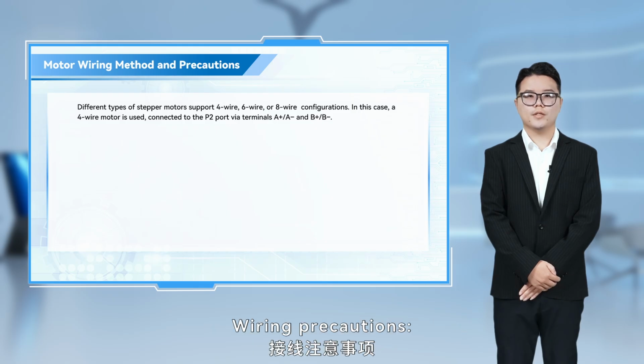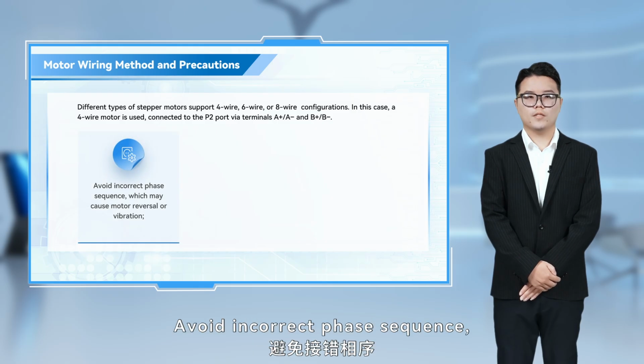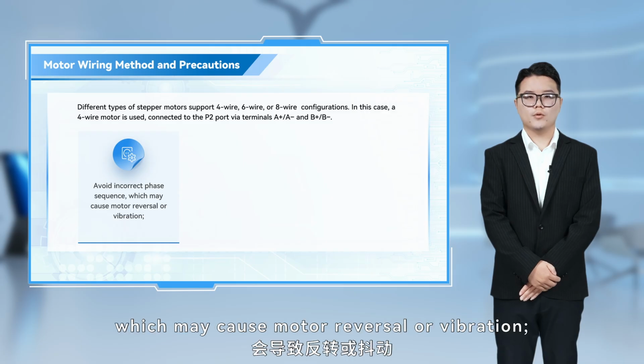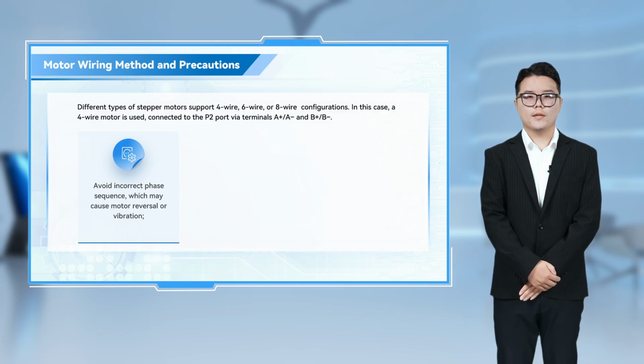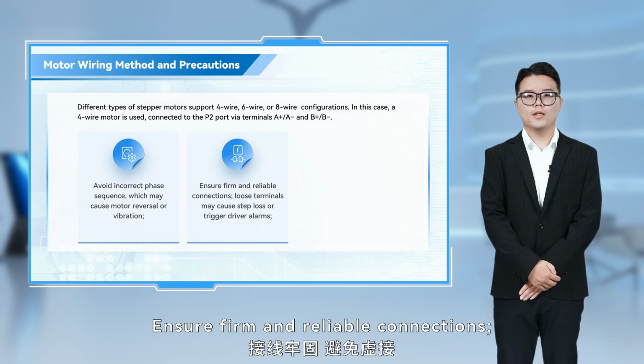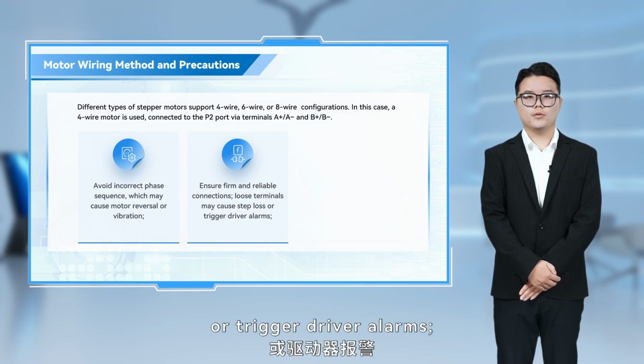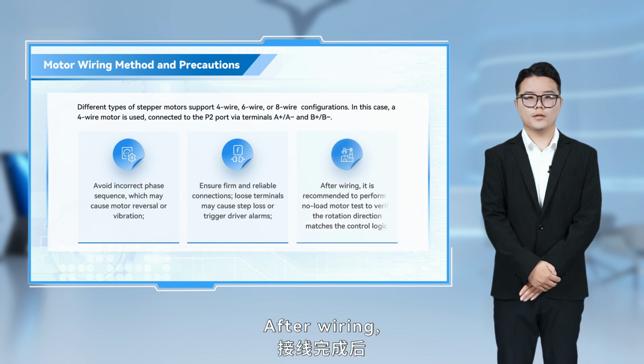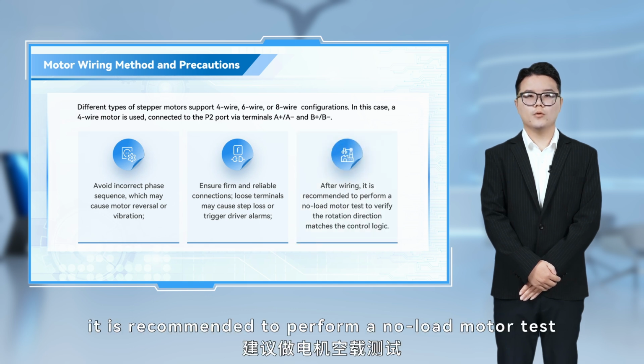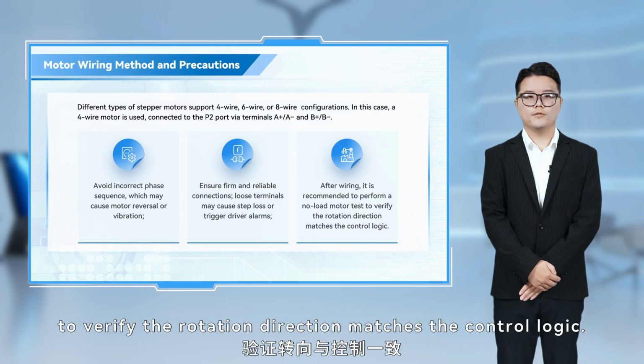Wiring precautions. Avoid incorrect phase sequence, which may cause motor reversal or vibration. Ensure firm and reliable connections. Loose terminals may cause step loss or trigger driver alarms. After wiring, it is recommended to perform a no-load motor test to verify the rotation direction matches the control logic.